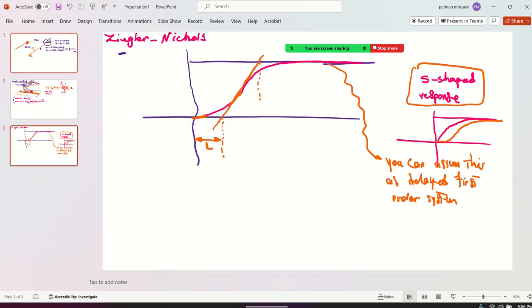This axis is time, and this is the output of the system Y, obviously. This value is going to be T, by measuring. And this is the K value, whatever it is, of the step response. I didn't say unit step, I said step response. K can be 75 Fahrenheit in your room, or 65 miles per hour for your car.